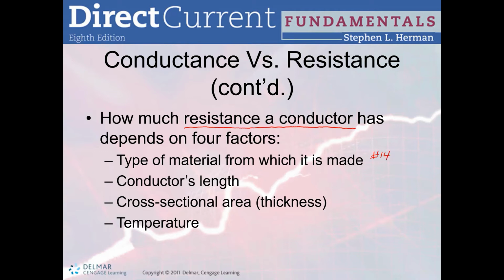And that one has an amp rating which is equal to how many amps? Do you remember? For 60 Celsius, you have an amp rating which is equal to 15 amps, right?